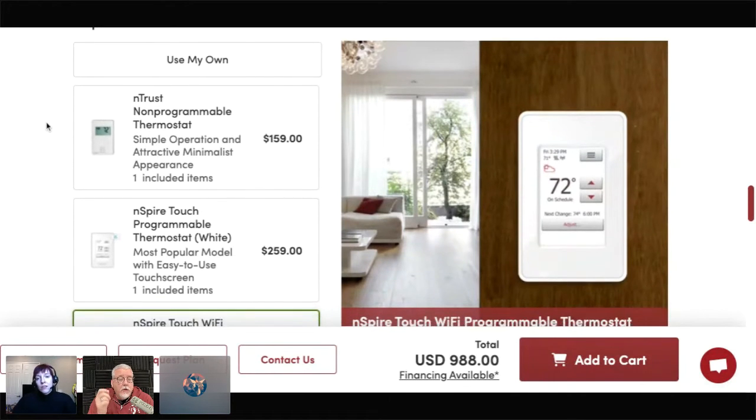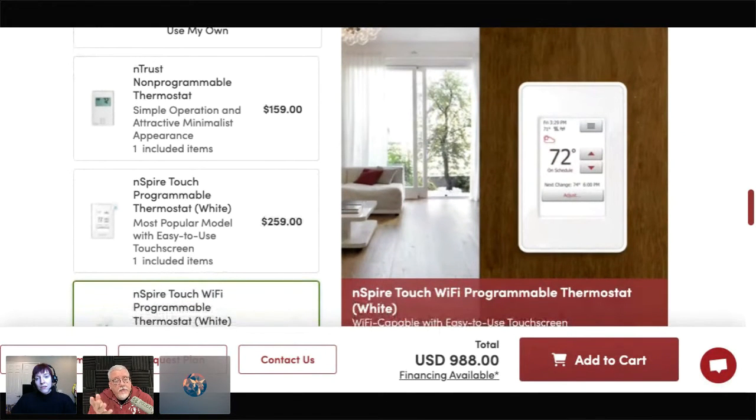When you're thinking about buying a control, not only do you want to ask the manufacturer of your flooring what the maximum temperature is, but you also want to ask them, first of all, is the product I'm interested in covered under warranty if I heat under it? Because obviously you want to choose something that has a warranty when you heat underneath it. And also, not only are you going to ask what's the maximum temperature, you also want to ask, with this flooring type, am I allowed to do a setback temperature? Can I go from 84 degrees during the day down to 70 at night? That's like a 15 degree difference. Am I allowed to do that?